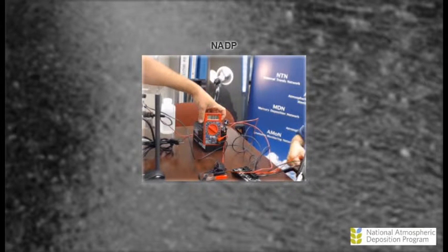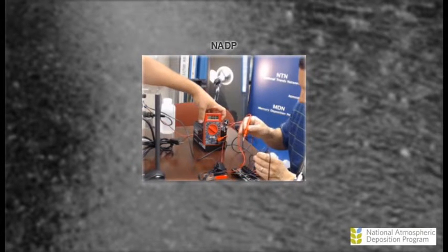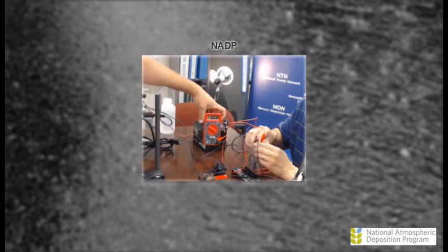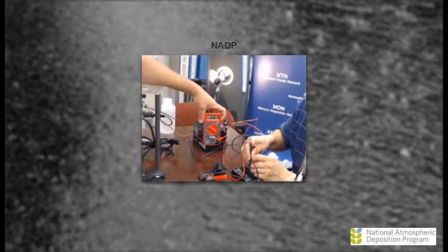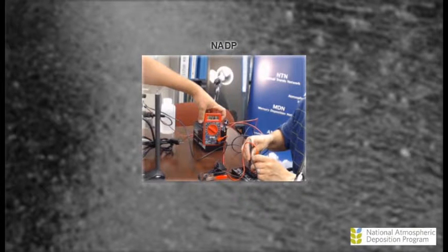I'm going to go ahead and reconnect the solar panel into our regulator. And what I'm going to check is first the lead into the battery. It's 13 volts, what we'd measured before. If the regulator wasn't working properly, we'd see far above that. You'd see probably 18, 19, 20 volts. The other thing we can check is the load center, what's going to the collector, and that's also about 13 volts.